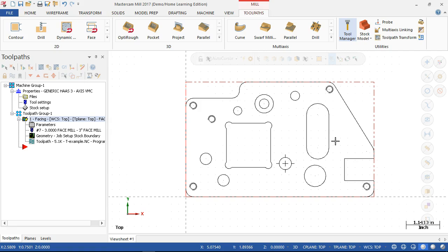If the machine shop manager ordered me 3/4 inch material and said, hey, you're putting this in the vise, then my job is to figure out how much torque I need to put on that vise to not bend this 4-inch piece of 3/4 inch material. Because if I go right to 90 foot-pounds, I bend it. I put a bow in it, and it may not be much, but it's not flat.